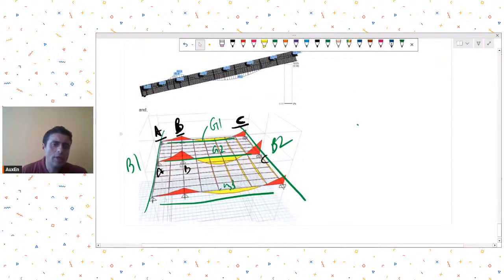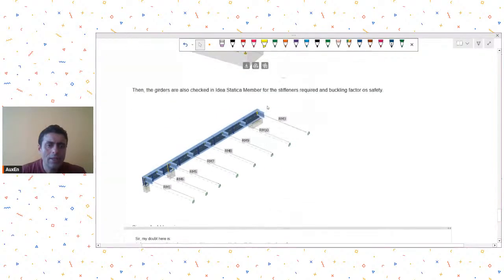So at the point B, you can very well observe that due to the continuity effect, even though the support given in ETABS is pinned, you will get a hogging moment over here due to continuity effects. At point C, he wants rigidity, so there is a hogging moment. At point A, there is a pin-like connection.